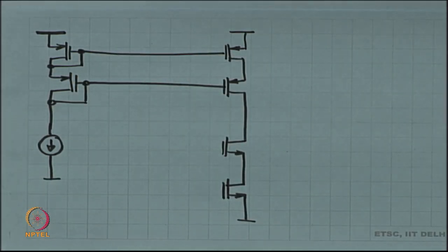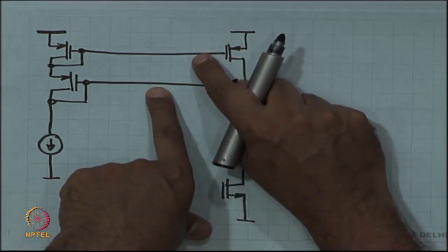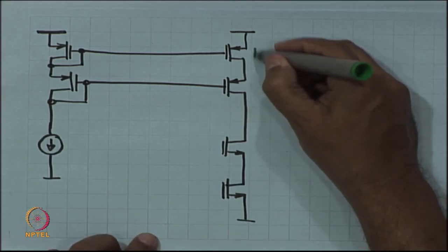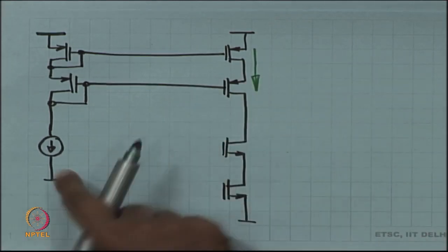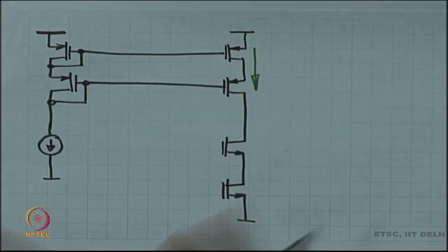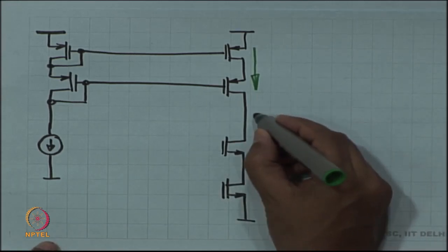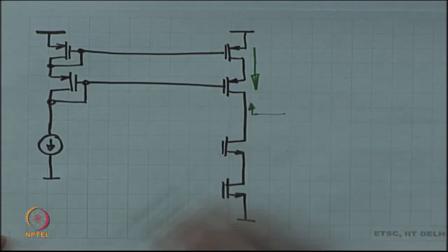All right. Now, these two voltages will be just right such that this bias current is the reference current. Is this okay? There is a Wilson current mirror. The impedance looking up from this node is just what it should be.